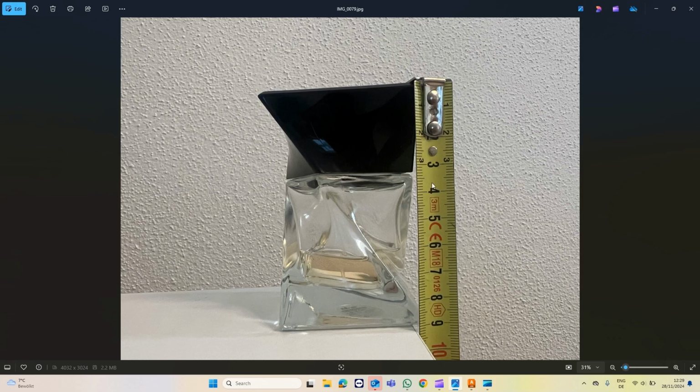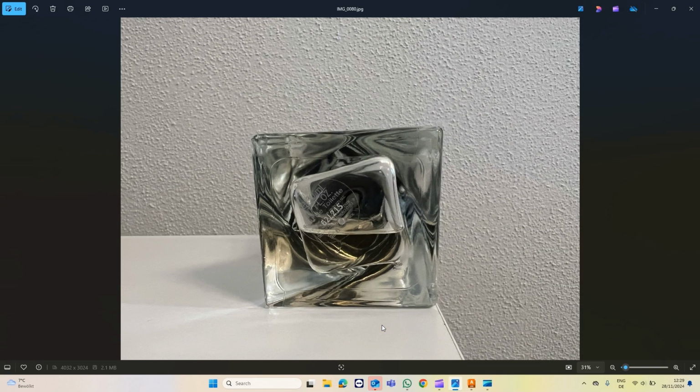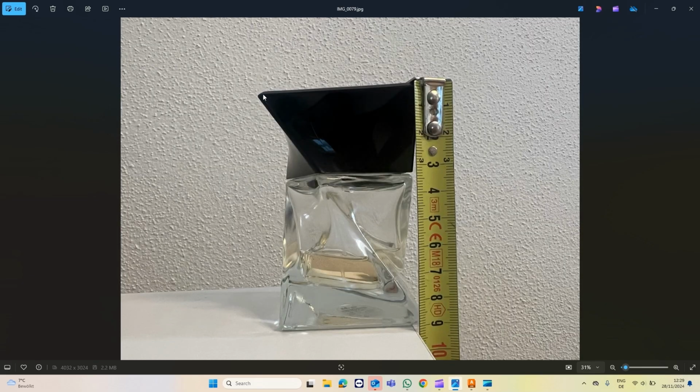So let's do that. Actually, let's do 3.2 for this line, 3.3 for that. So we'll leave 1 millimeter gap between the two. That's important when we get all the detail in. And we can see here we've also got a very nice chamfer running around there. That's all interesting tools. Let's see how we can build them.